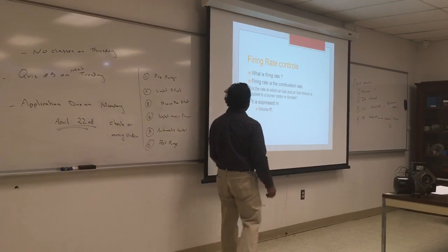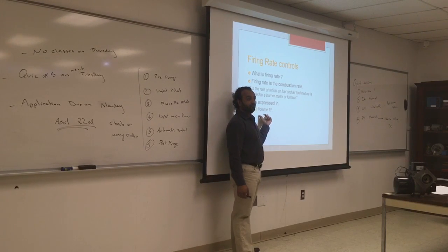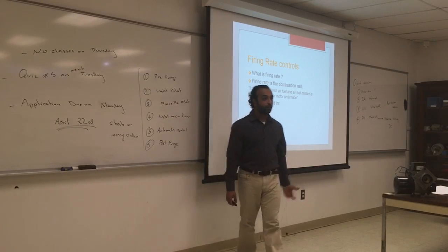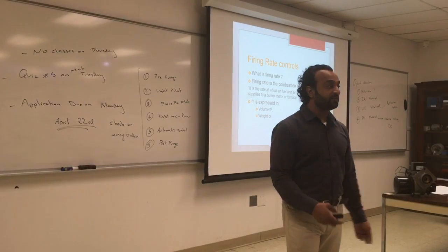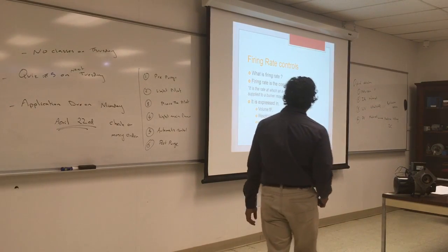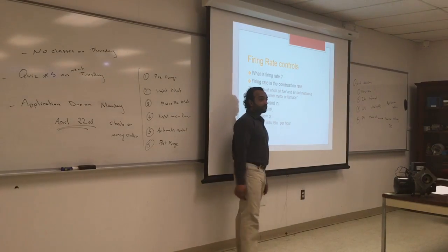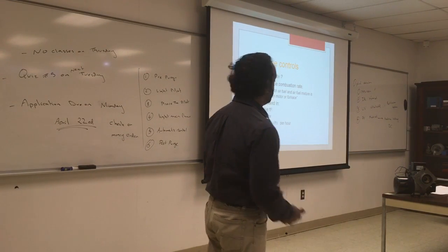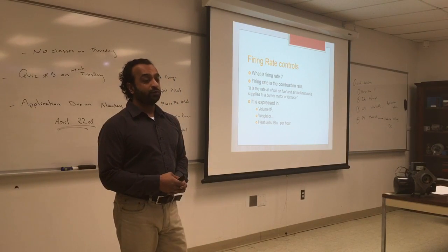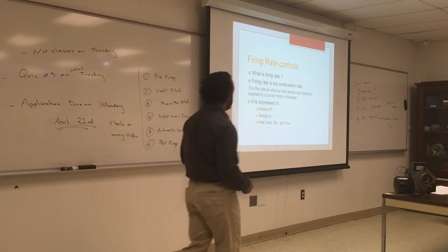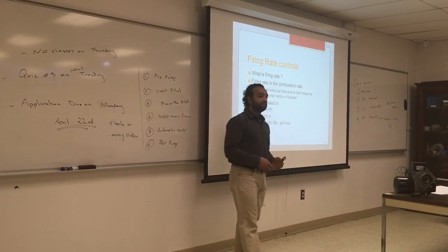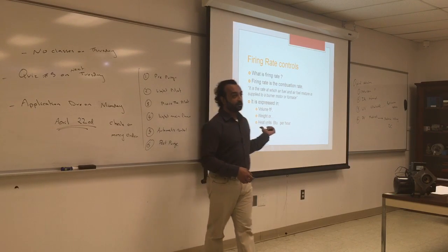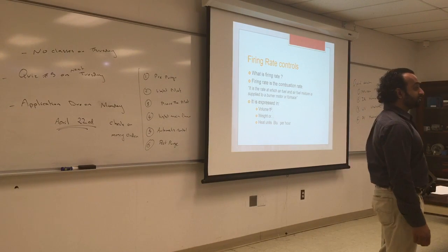It can be expressed in volume, in cubic feet, if you have gas. It can also be expressed in weight, if you have coal or oil. So there are different expressions for firing rate, and heat unit BTU per hour. So you'll see a firing rate in volume, and you have to convert that into BTU. You'll also see it in weight for coal or heavy fuel oil, because it's mixed with other substances. So you will see firing rate in volume, weight, or BTU. Remember that, because that could be one of the questions in our quiz.